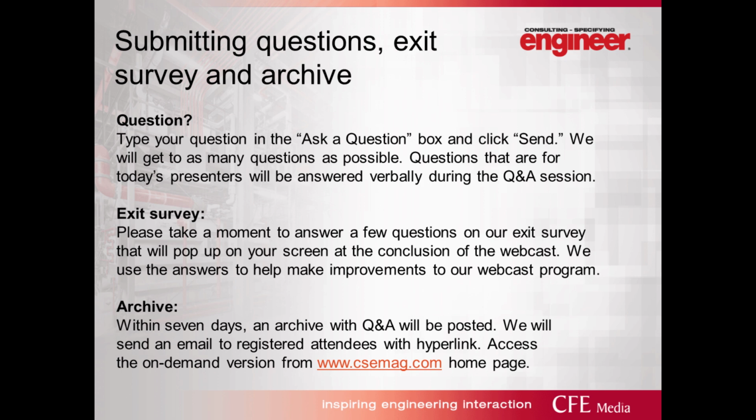Also, the large motors are the key components that drive your generator size up. So use VFDs or self-starters on larger motors to decrease that inrush current.